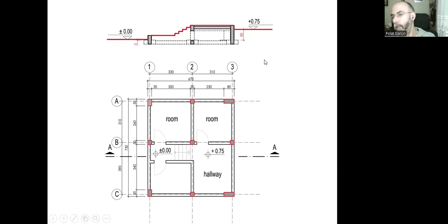If I prefer the second alternative, then it will be something like this. I go for 80 centimeters deep and I'm going to place my footings, but on this side, the footings will be so close to the surface. That means that there is this risk of frost and expansion. And that's something we don't want.